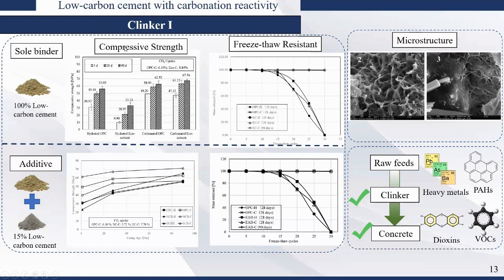And we found through compressive strength that this material has a hydraulic behavior, so it can react with water only, but it only achieves relatively low strength compared to our reference OPC. This is commercial OPC. After 90 days of hydration, it can only achieve 33 MPa compared to 56.